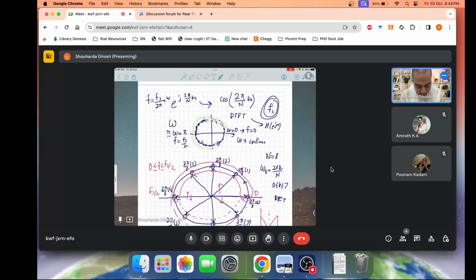evaluating. Omega equal to 0 implies zero frequency, or DC. Omega equal to π implies that you reach half the Nyquist rate. So 0 to 2π, where 2π is fs, which is the Nyquist rate, and your signal has a bandwidth of Nyquist by 2. So the maximum frequency of a signal is represented over here, because you have not acquired anything more than the maximum.